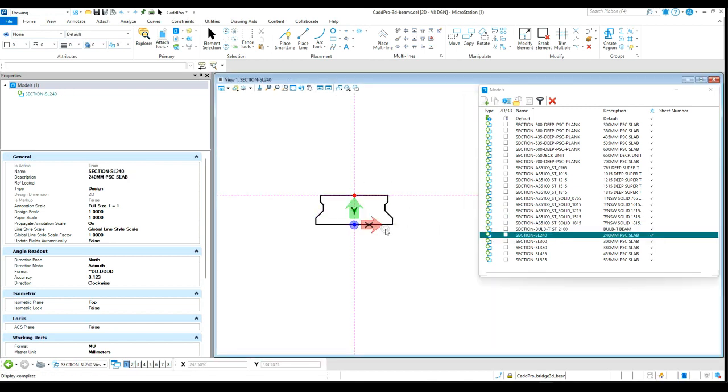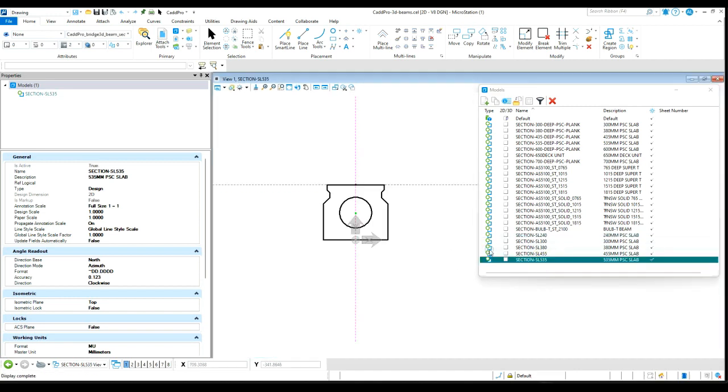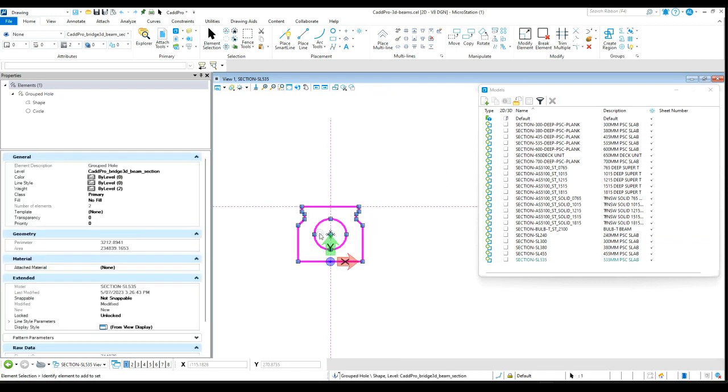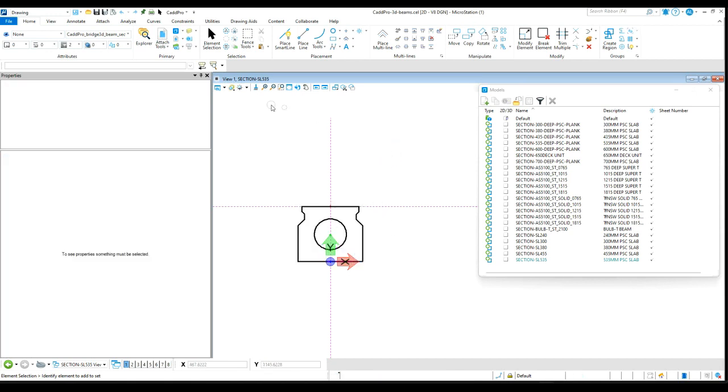Likewise for this one, there wouldn't be any trimming of the top flanges. And we've got one here that's a group tile, so it's got a void in the center there. So as long as these typical sections can be extruded by normal solid commands, we should be able to use them in this.